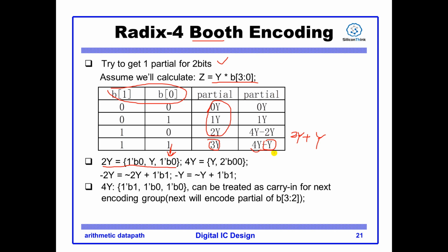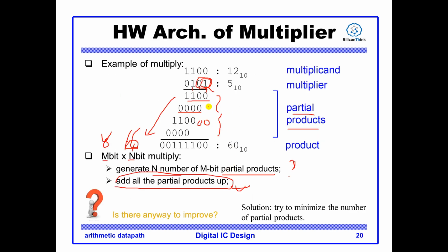You can say it's easy to get for 2's complement encoding of signed number. So minus y can be represented as invert all bits of y and plus 1. The plus 1 can easily be done. You can just append it at this point.